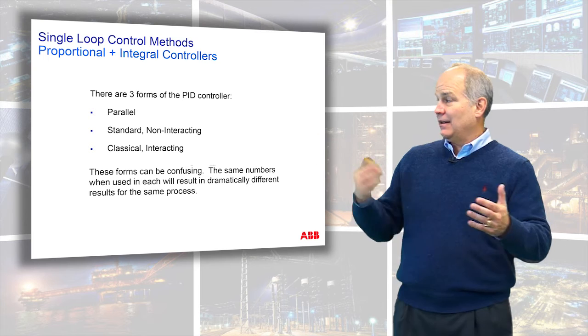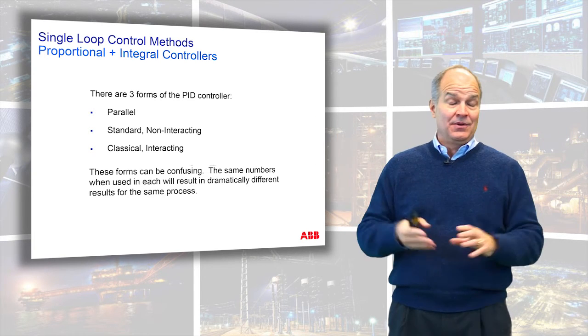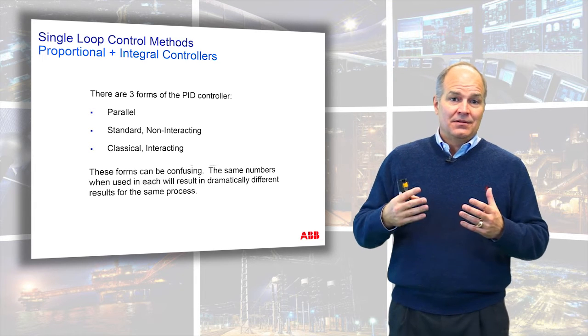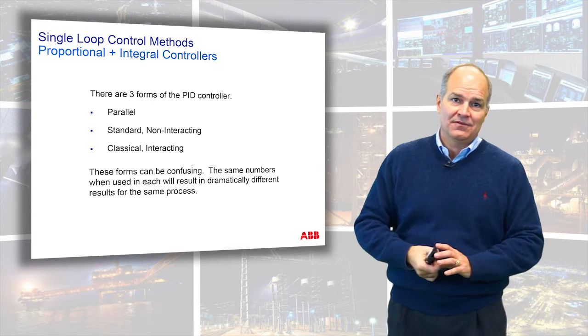I was at one place where they had one manufacturer and I dumped out their mode. Half of them were parallel, half of them were standard, and the controls were all a mess. And the E&I staff just said, we don't get tuning. The same numbers on the same loop, they don't work. And it's because mathematically they were being used differently.